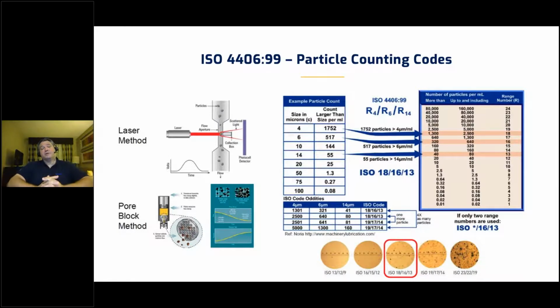And then there's photocell laser methods. This is using a laser or a light source to look at the reflections or the shadows being cast by particles, and from that you can measure size and even shape. Some of the instruments today are very sophisticated, and they can tell you not only size but shape of the particles, and whether they're sliding, cutting, spalling, different things there.